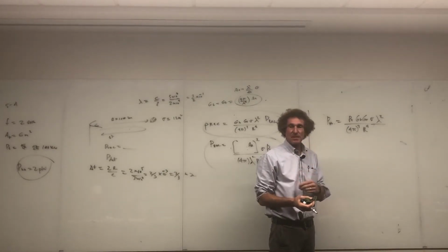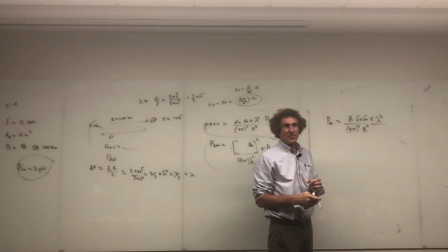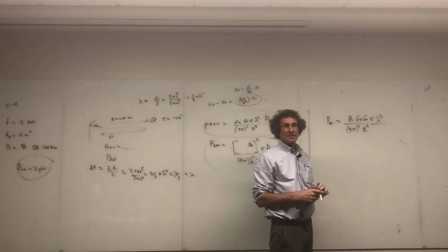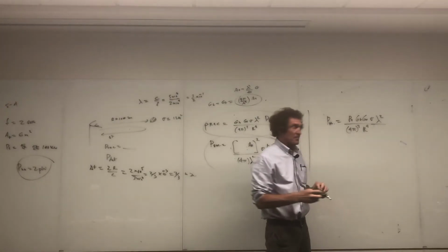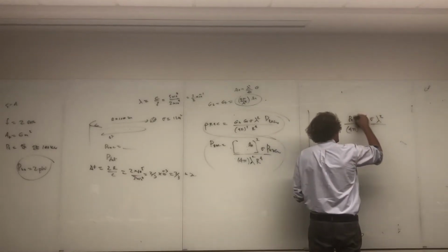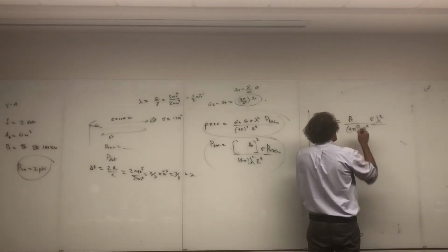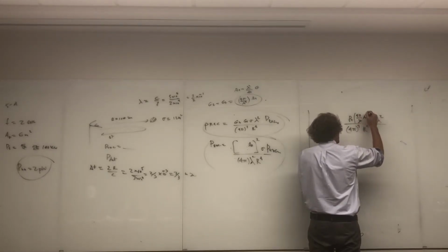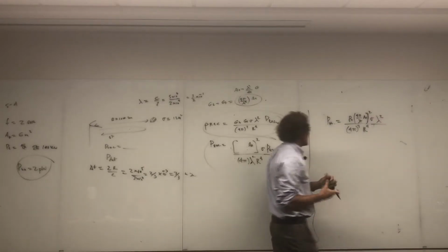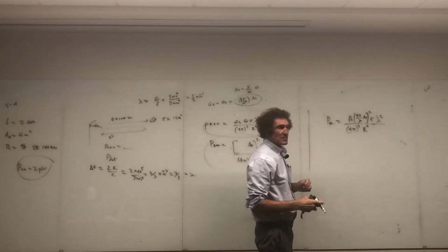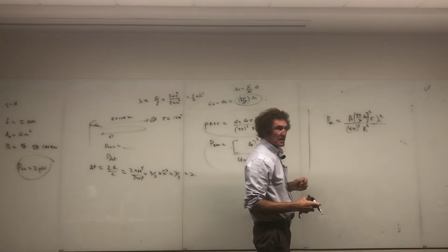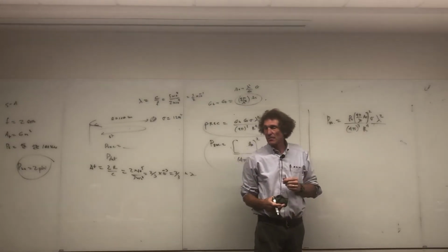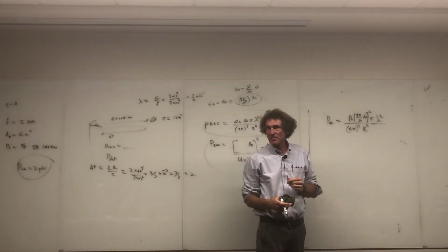We can go through it step by step and how to get it. The only thing I'm going to do is replace the two gains by 4 pi over lambda squared times the aperture, and then I have to square that. Now I have a single equation for received power in terms of transmitted power. Sorry for the mess up. You all with me on this, class?